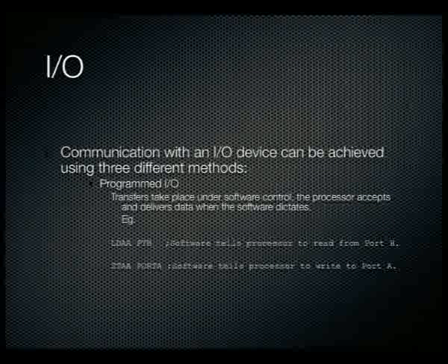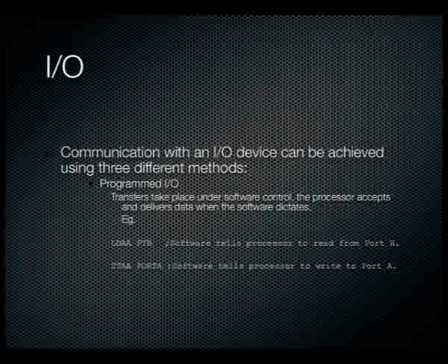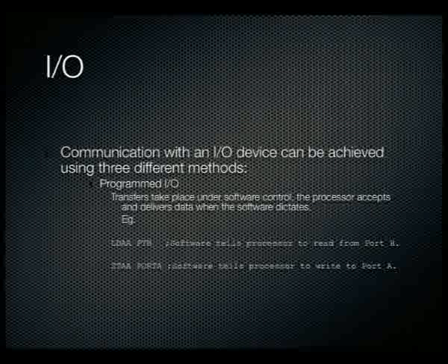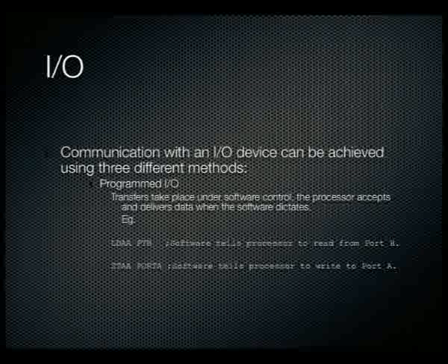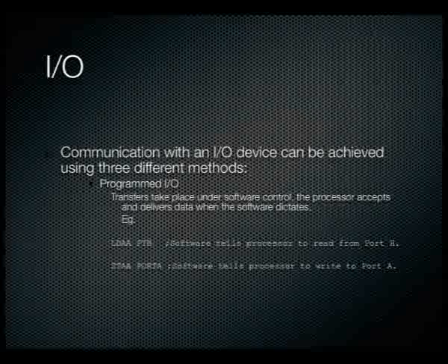Communicating with an I/O device can be achieved using 3 different methods. One is programmed I/O, which means the transfers take place under software control, so the processor accepts and delivers data when the software dictates. So simply the program dictates when data is moved around.